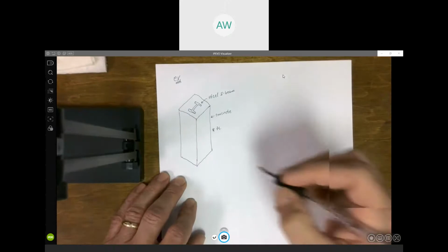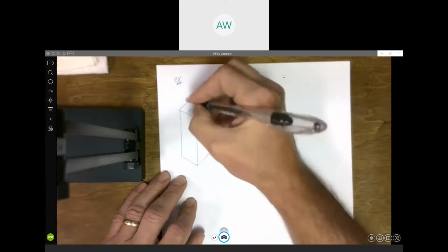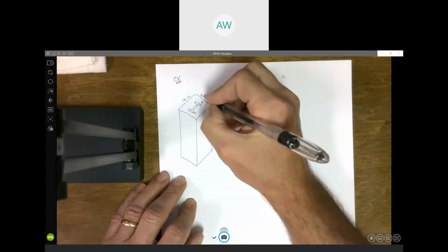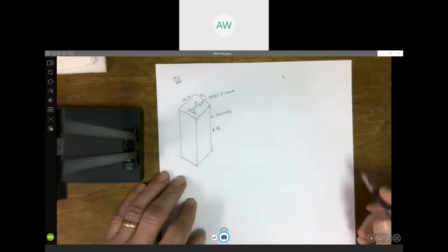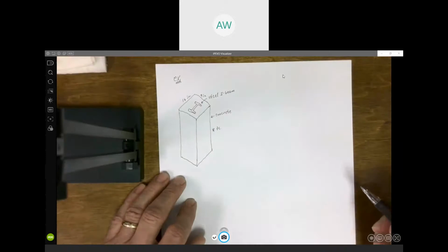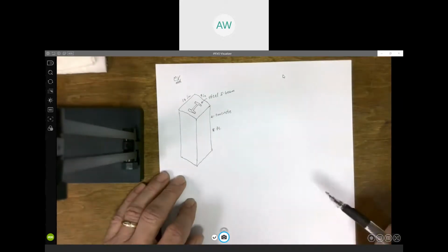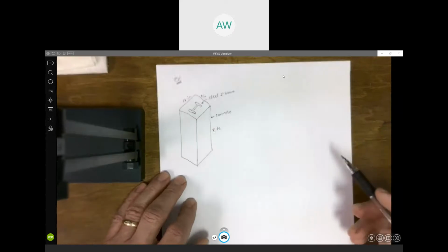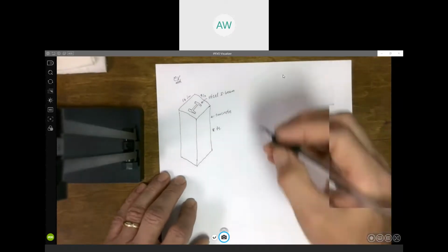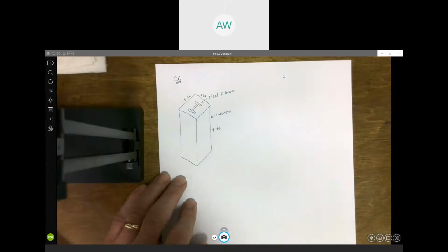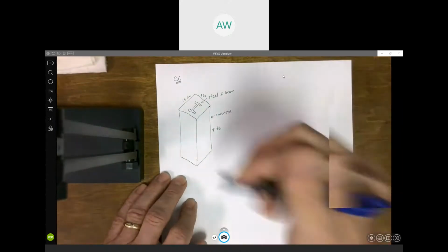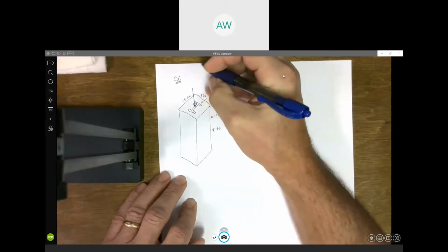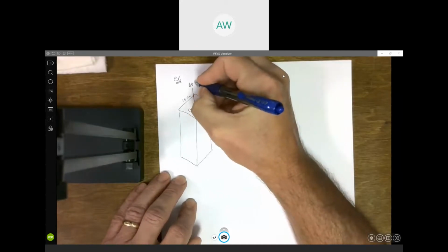And dimensions, this is 16 inches by 9 inches. So it's a 16 by 9 rectangular column, concrete with the steel I-beam going down the middle. And we are going to apply a vertical compressive force of 60 kips.